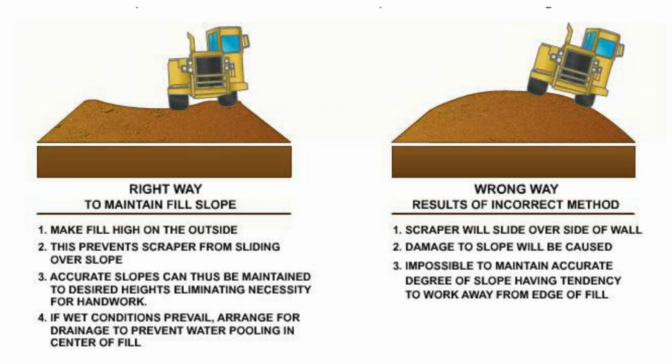And you just know that OSHA is going to want to know why you rolled a very expensive vehicle, and your boss probably wants to know why his $2.7 million scraper is in the shop for $250,000 of repairs. If you operate as on the right side, you also lose control of the slope because it's very difficult to grade. On the left-hand side, if you have raining conditions, if it's wet, you need to have ditches and perhaps sumps to keep water out of it. Remember, most of the time we're going to be moving clay or cohesive type soils that are going to really like being wet. So we need to be aware of that.